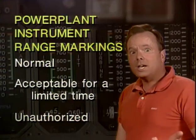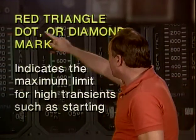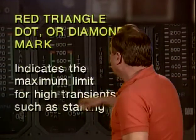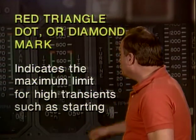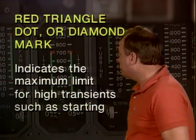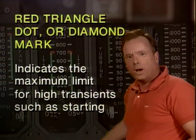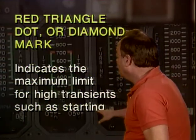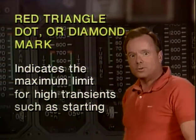Now occasionally you see something different, something I've never seen, by the way, as a pilot, and I've asked other pilots, they haven't seen it. But the FAA says occasionally you can see a red triangle or a dot or a diamond mark, and they say, all right, super mechanic, what's that mean? Well, that indicates the maximum limit for high transients, such as starting. In other words, sometimes the ITT on a jet engine goes real high during start, higher than would otherwise be acceptable. That's called a transient, and that might be allowable up to a red triangle, dot, or diamond mark, and they want you to know about that.